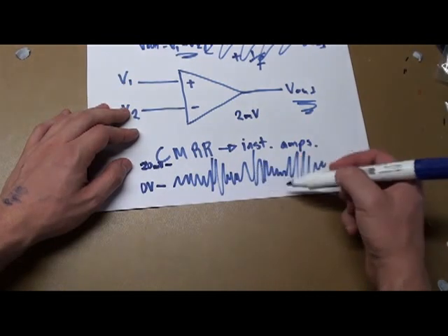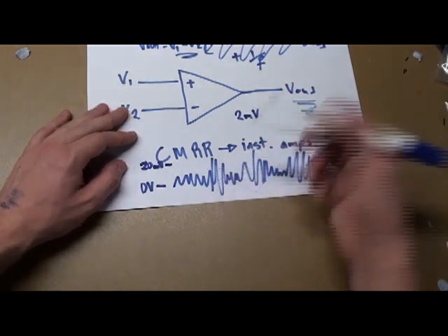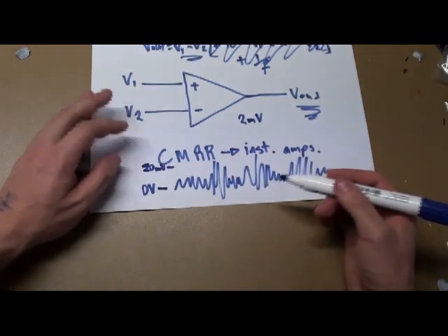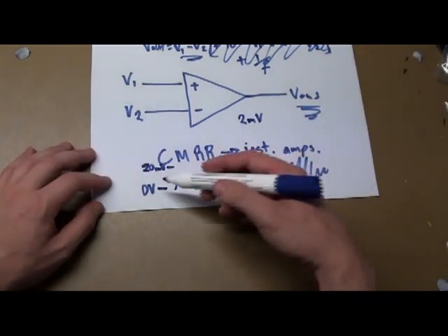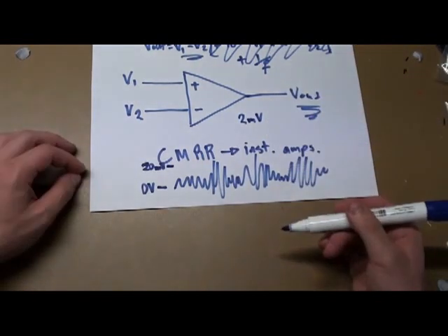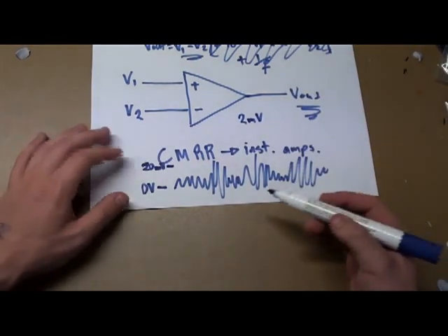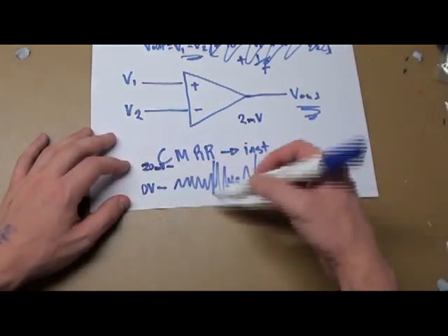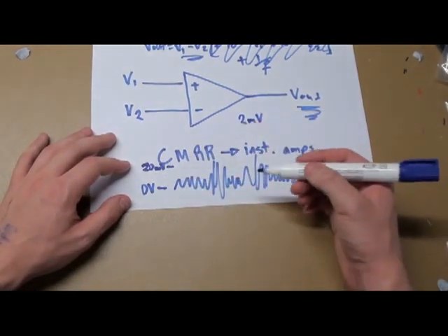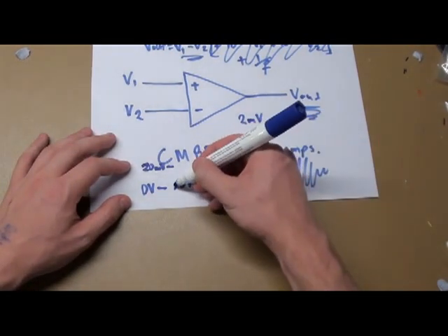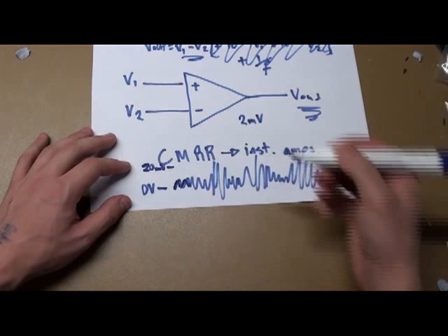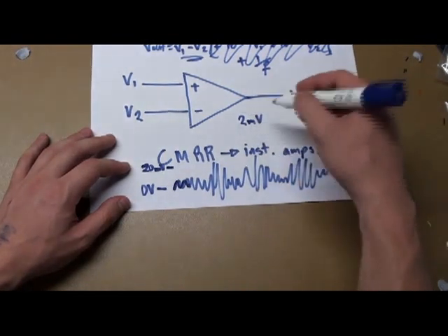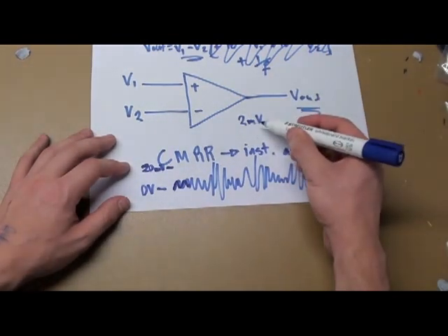So that means there's signal existing in your wires without you connecting anything, and that's because we have radio waves and all sorts of stuff going through the air, and it just naturally gets picked up by things that conduct. So if our signal is 2 millivolts, it might only shift it up a little tiny bit, and that can be pretty hard to find. So we've got to do other stuff to get this 2 millivolts to where we want it.